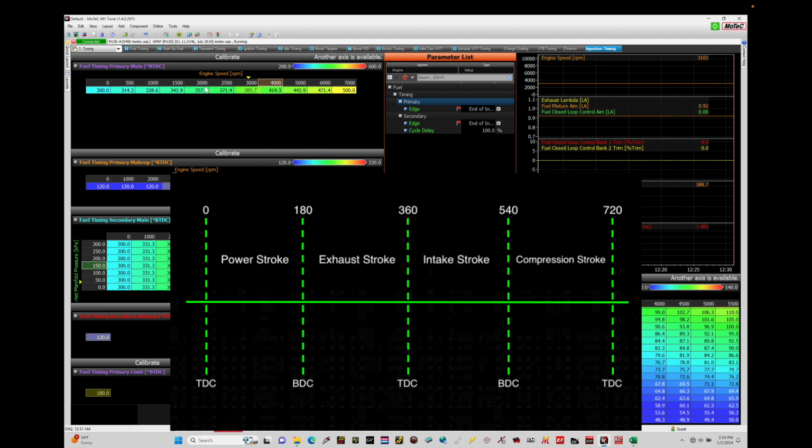We know the piston there is at top dead center. As our piston moves down to bottom dead center, that's going to be the equivalent of 180 degrees within this cycle, and then we'll see we're going to be starting into our exhaust stroke. Then we'll find the piston's going to move up to top dead center. We'll be at then top dead center between exhaust and intake stroke.